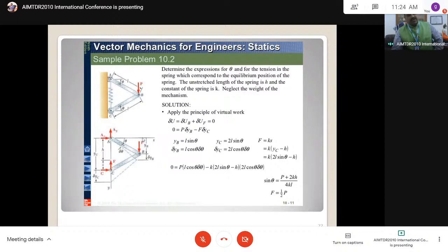you apply load P here. These are the hinge joint's two reactions, because it is a planar system. We have 3 degrees of freedom. Out of 3, rotation is possible. This translation is not possible, this translation. That's why A_x, A_y. Similarly, as far as this roller is concerned, rotation as well as translation in this direction is possible. Now, the unknown is in the vertical direction.